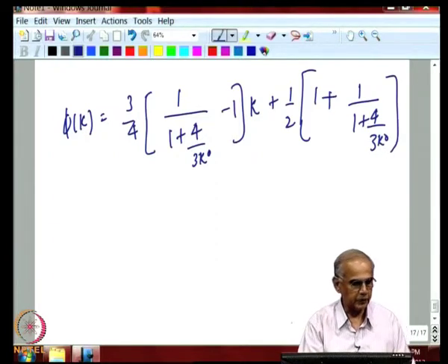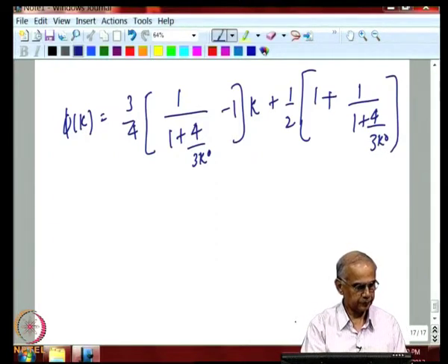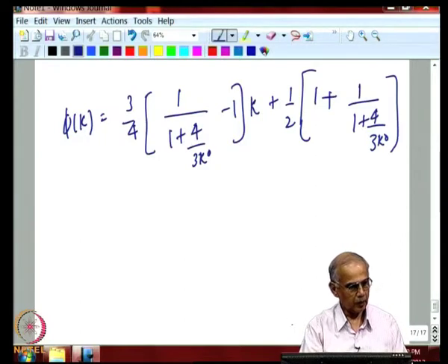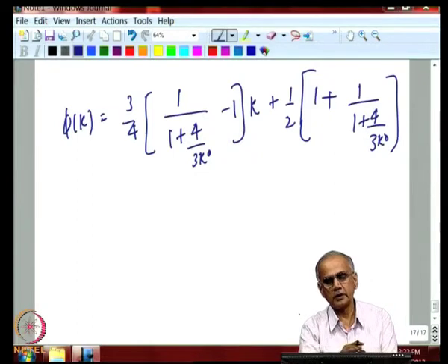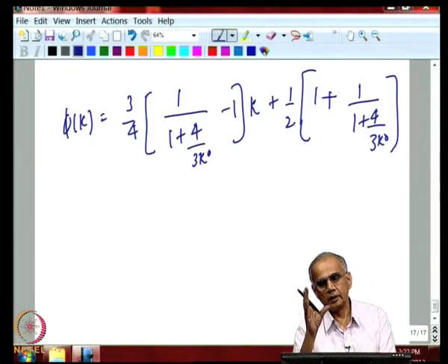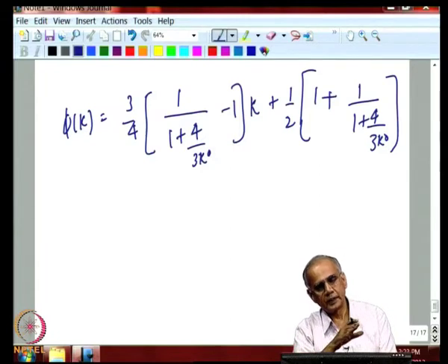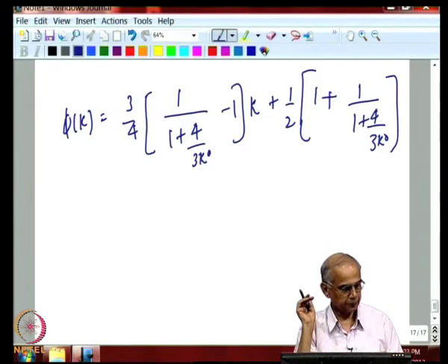So, that is the expression for the temperature profile. And notice that this result is independent of d, that parameter which defines the fraction of radiation lying between lambda 1 and lambda 2, that does not explicitly come in this equation. But of course, the q star, the radiated flux depends on d.